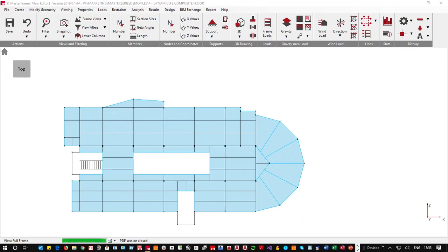If you convert the steel beams to concrete, will it give the same results? No, it will not. The stiffnesses will be different, and you would also be working to a different publication. You'll be working to the Concrete Society publication with its recommendations.